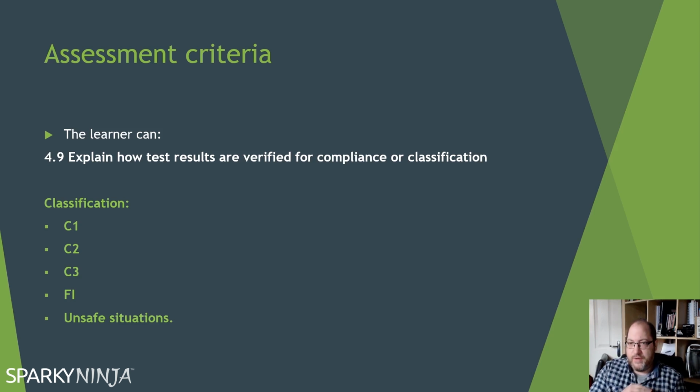So if I have no earth, then that's not dangerous, so it's not a C1. But in an earth fault condition, which is a single incident, it will become dangerous, which would be a C2. So your C1s and C2s are potential danger or danger present. That would be an unsatisfactory report. C3s is when there's improvement recommended. We used to do codes for all silly non-compliances, but this is only going to be used where you have a good advisory to improve something.